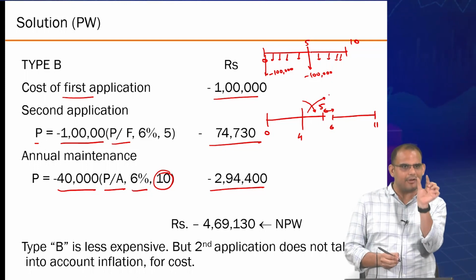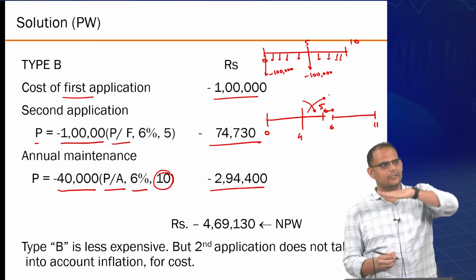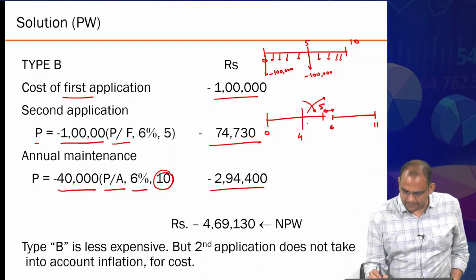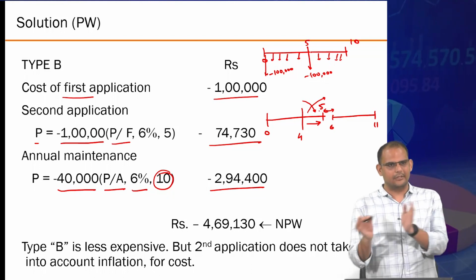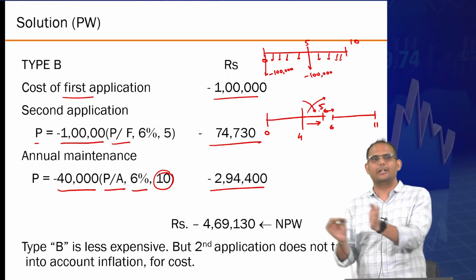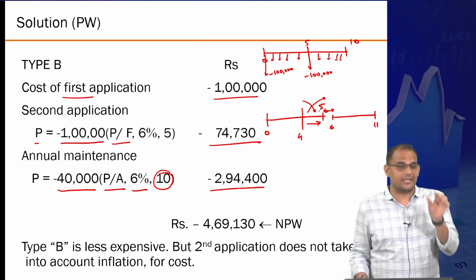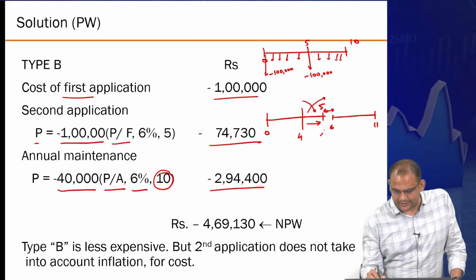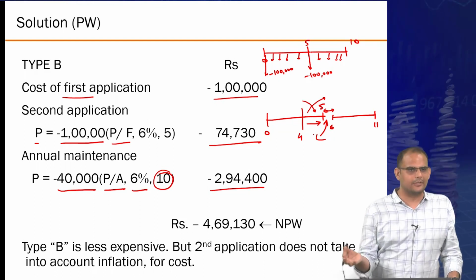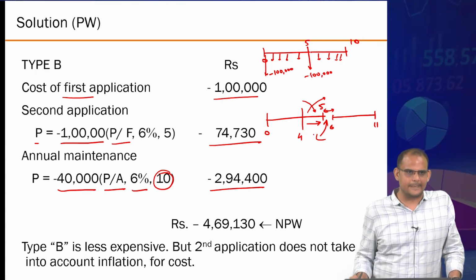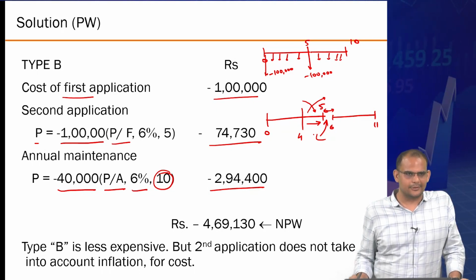So in year 5, while your road is degrading, you are also putting money to rebuild it. And by the end of period convention, that comes at the end of year 5, not at the 1 year gap of 5 and 6. Because otherwise there is a service disruption. In this 1 year, there is no road service. So that is not a good alternative. Still doubt?